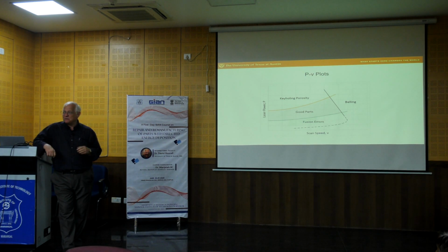We only had the research machine in Texas for doing powder bed fusion, and so I was very early doing metals. We were the only game in town, and so we were the first to observe this balling phenomenon, which is basically little tiny spheres of metal that sit on the surface, and they're approximately the size of the laser beam, or it happens with electron beams as well.